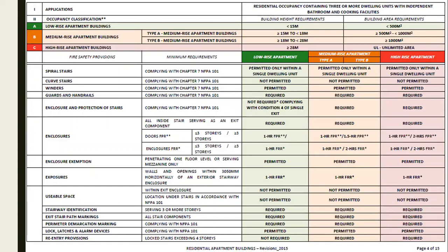Okay, we'll give you a quick idea about the handrails. The handrails have to be continuous, starting from the edge of the walls, and to be on both sides, right and left, for the stairs. It should be continuous even within the landing of the stair and the diversion, etc. It has to be continuous without any cutting.